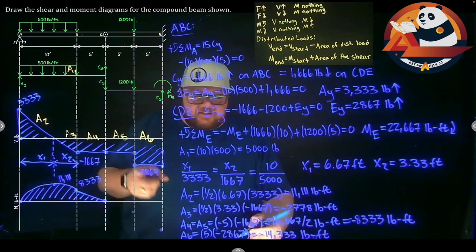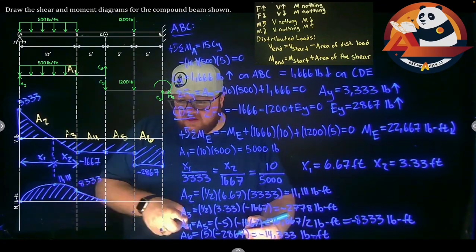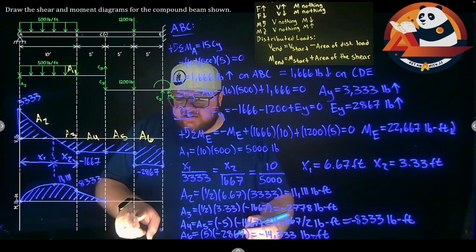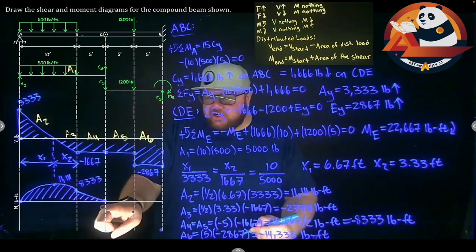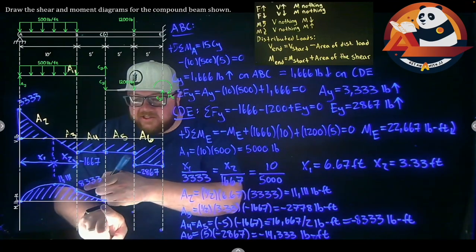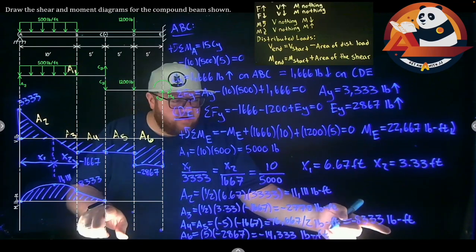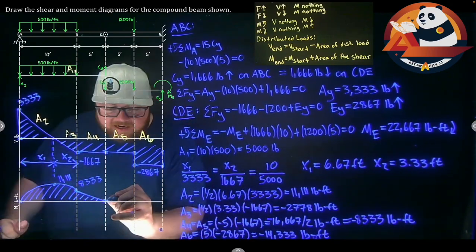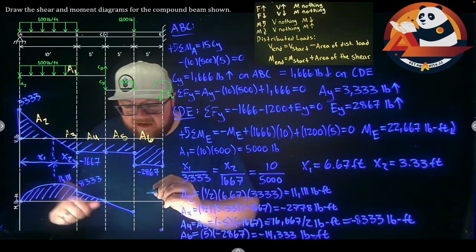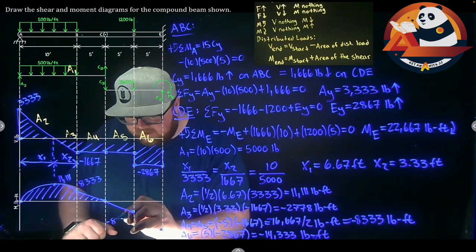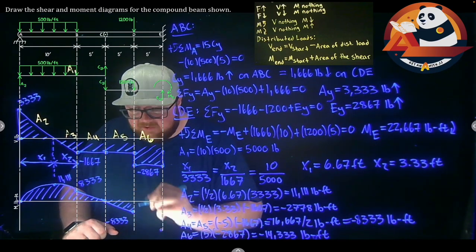So we could have just made this one area, area 4 and 5. We've gotten 1667 and just straight line all the way through. We would have gotten to negative 1667. But we split it up into 2. We should hit 0 right here. But so 0 minus 8333, continuing our straight line on, down here to negative 8333. Which should be our next piece that we need to work with.